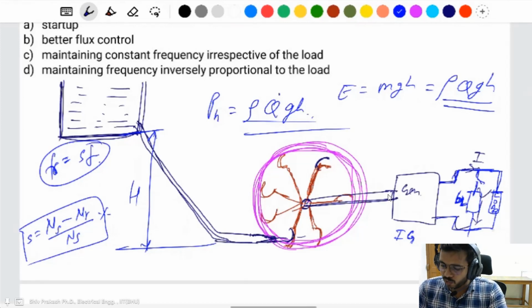When the load increases, this switch is opened, or this is controlled. The switch is controlled by some function. Then the power in the ballast load is reduced at that time when the load is increased. Then the whole current will stay constant, so the current will not change suddenly. Then the generator speed will not change, and the frequency will be maintained.